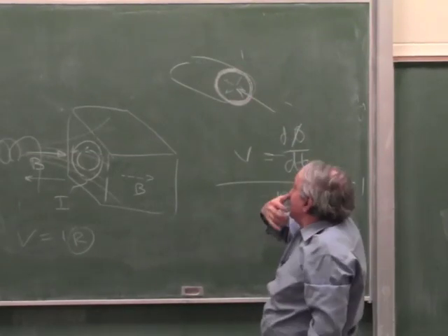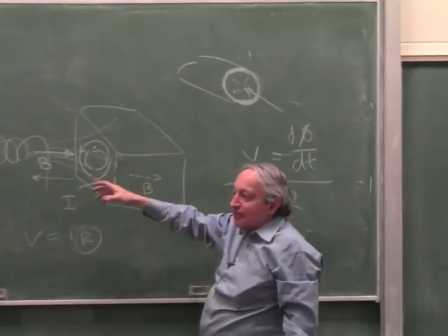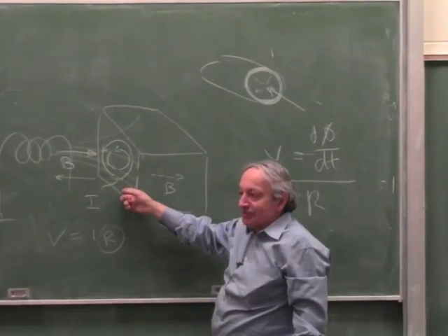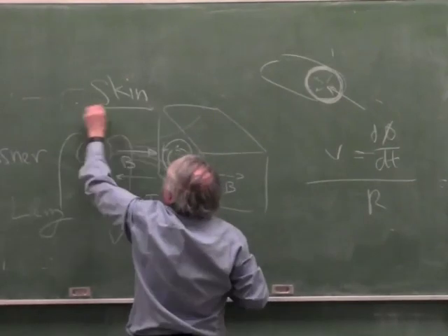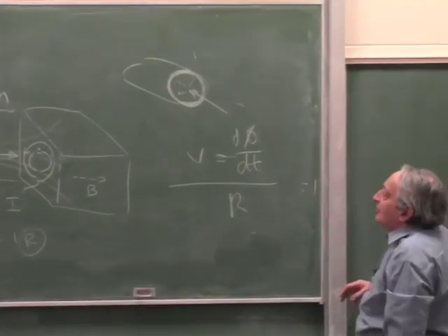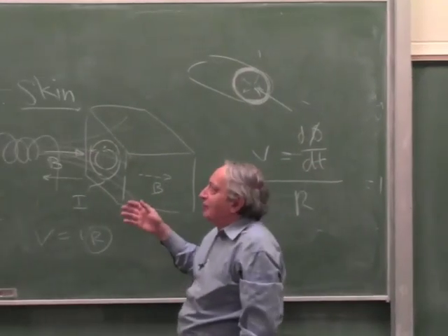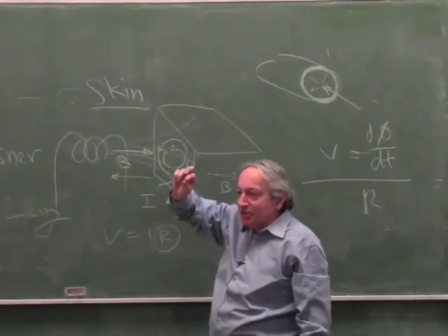So the reason why the shielding at high frequency is bad is that this appears much more resistive than it really is at high frequency because of skin effect. Skin is like human skin, it's not the name of a person, right? Okay, good. So what do you do if iron is bad for skin effect, because in ferromagnetic materials the skin depth is much less.